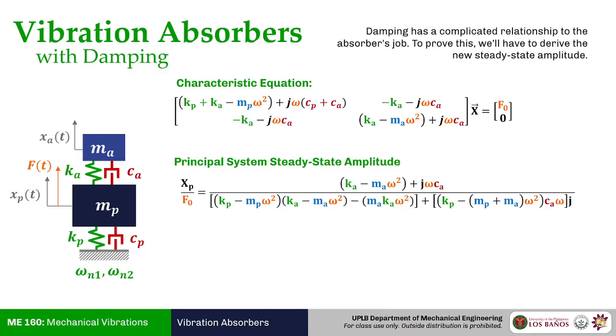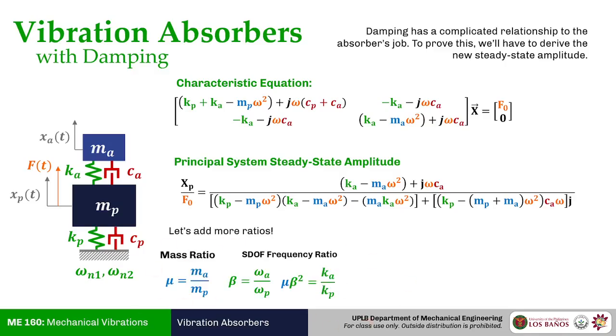The first thing that we have to recall is that we have to use our ratios to the T right now. So here are our established ratios from before. You have our mass ratio, we have our frequency ratio, and we have our primary frequency ratio here. We're going to add a fourth one. This is called the mixed damping ratio. Now, don't be fooled. The mixed damping ratio, the zeta mix, is nobody's damping ratio.